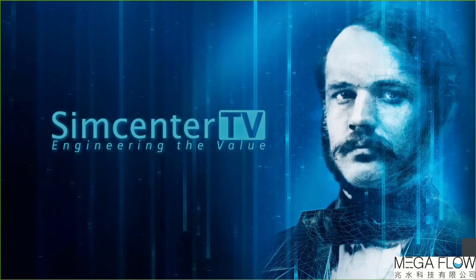Okay, there is another question about the automatic CFL. The question is about the target AMG cycles, which indicates how aggressive the solver is. Does it mean the higher the number is, the more aggressive the solver is going to be? Yes, that's exactly how it is. The default value is 4.